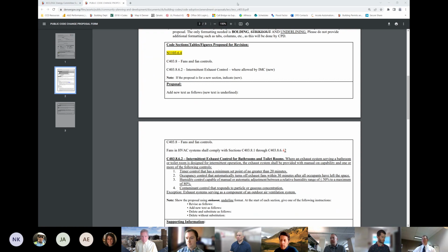If you go into the bathroom and your fan is on a switch, often you leave the fan running, you forget to come back. 2 hours later, you go back either when the noise has annoyed you or, with super quiet ones, you might not remember for a while. There are some really quiet bath fans out there. And so this will reduce energy, because what's happening is you're basically bringing your building negative and having to condition that air that you're exhausting.